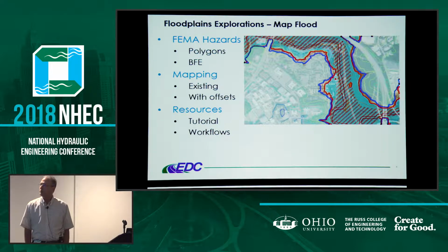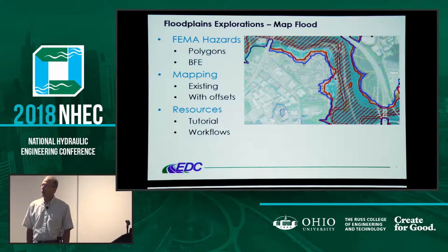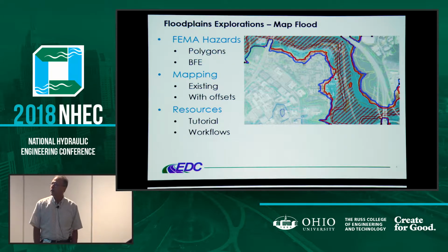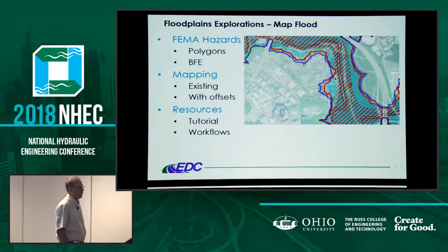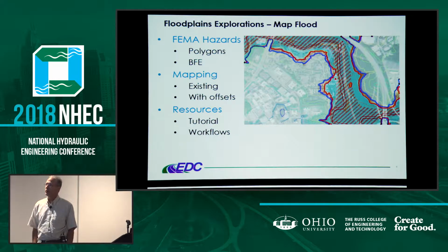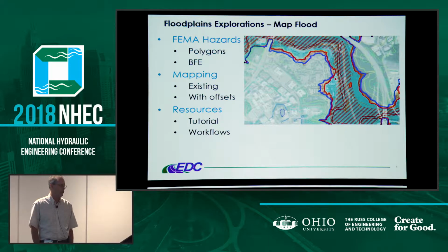Now, another tool that we've been developing started out with a description of a fast floodplain modeler, and it specifically allows you to get what-if scenarios when looking at the floodplain. That allows you to bring in the FEMA flood hazard maps and put them on display, and using whatever elevation data and base flood elevation data is available, you can delineate what the floodplain would be just doing digital mapping, and then quickly say, well, what happens if we raise the base flood elevations by a foot?